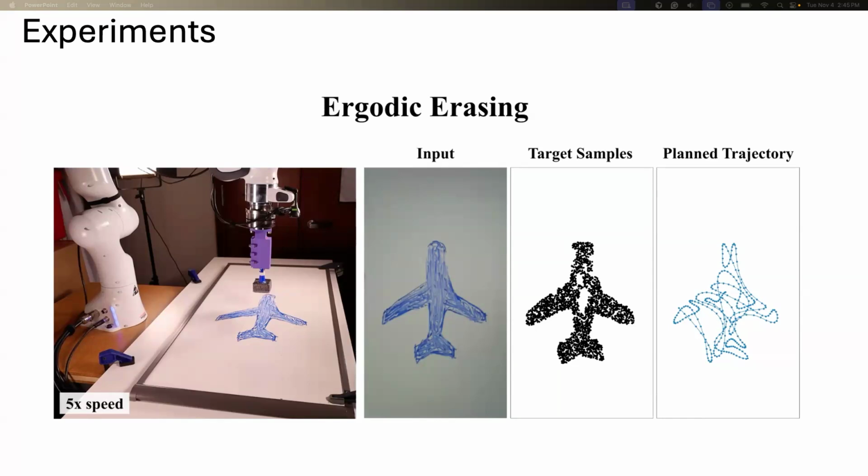I think another more interesting one is not just the position of yourself making your spatial distribution, but if you have a full 6DOF vehicle with a rigidly mounted sensor, you take the boresight of that sensor and project it down to the ground, and that's the point you're actually sweeping around and planning for. But you're planning a true 6DOF, dynamically feasible trajectory for this robot to ensure you're optimally sweeping around that sensor footprint.